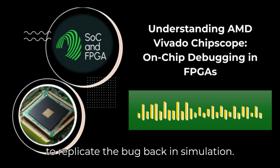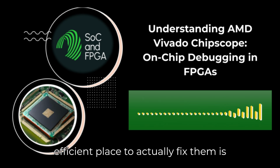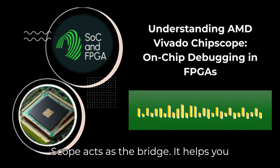And finally, remember the ultimate goal. Try to replicate the bug back in simulation. While Chipscope is essential for finding those tough bugs in hardware, the most efficient place to actually fix them is almost always back in simulation. Find in hardware, fix in sim. Exactly. Chipscope acts as the bridge.